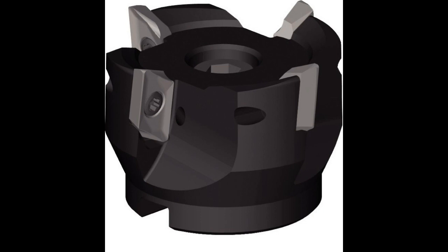They're very accurate, and those inserts seat right in very accurately, so they can be changed in and out, and if your tolerances are appropriate, you don't have to reset the tool. The insert does have a radius on it, and so if you were to cut a feature that leaves a sidewall, you have to account for whatever the radius that's designed into that particular insert.